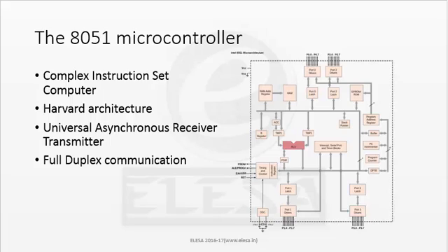Our main focus is going to be on the UART module along with two timers. The UART module supports four modes of communication with support for multiprocessor communication. Timer 1 is usually engaged to generate the required baud. The transmit and receive interrupts acknowledge the completion of data transfer.